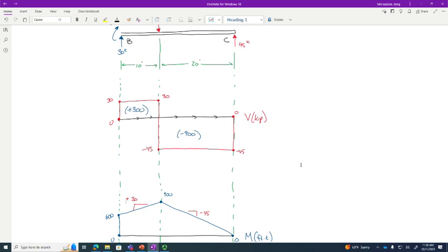So what this led to was us being able to just sum up some terms, right? The problem with a beam is it doesn't really work like that. For beams, if I put, let's just make it simple, 20 kips, do I get the same moment if I cut a section here as if I do here?